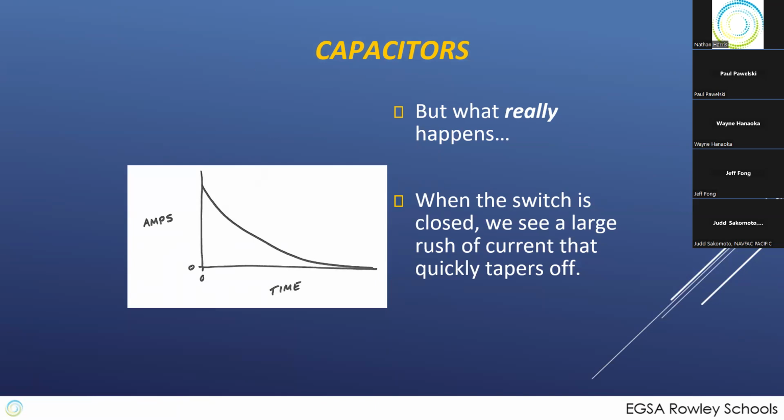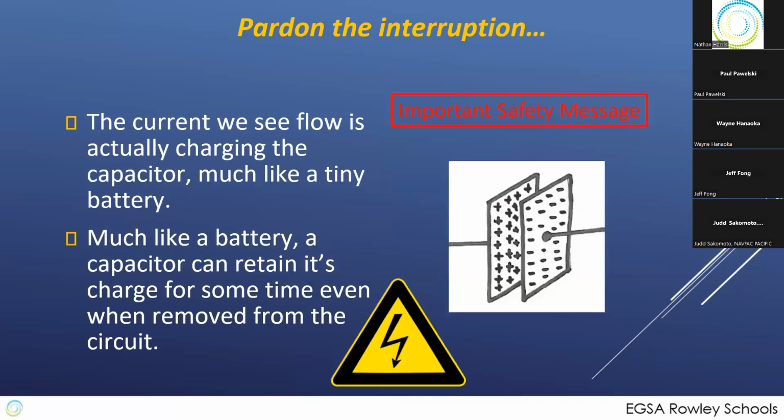And the thing that you get is when they're in as close as they can be with the amount of voltage trying to push them, no more flow occurs. Think of this like a Japanese train being filled up by people going to or from work. Okay, the number of conductors on the outside pushing determines how many people they can squeeze into that car. And that's the same thing that happens with a capacitor. The electrons push in on one side because everything balances out. Electrons are pulled away from the other side. The more voltage we got, the more it goes in.